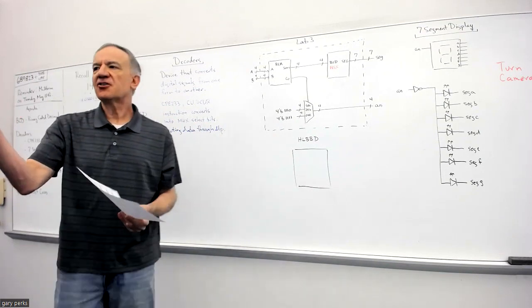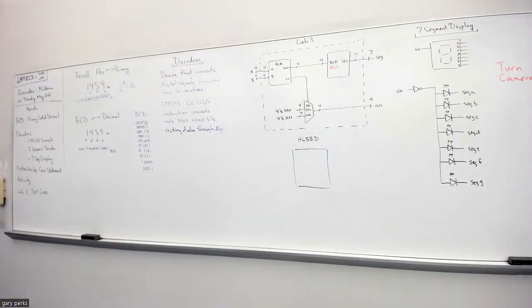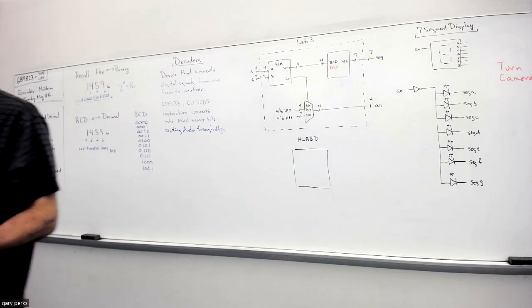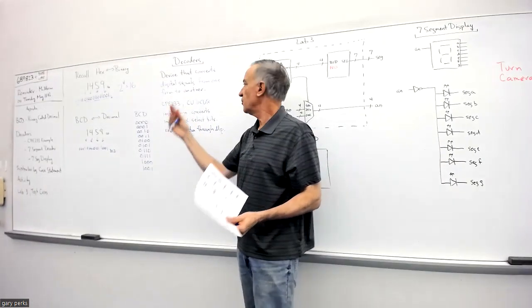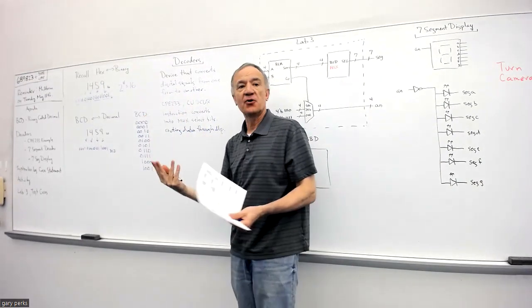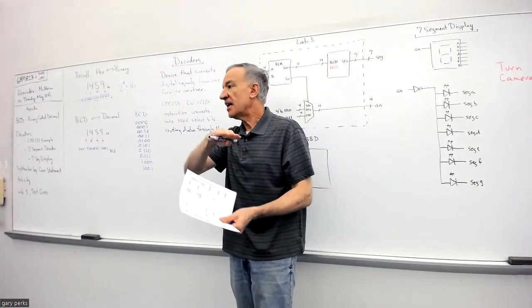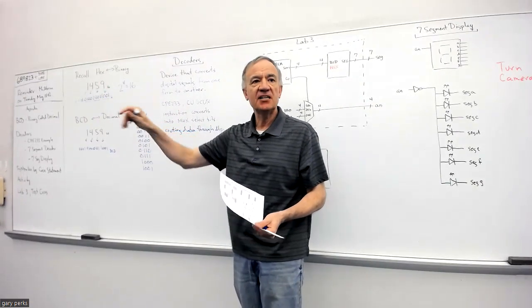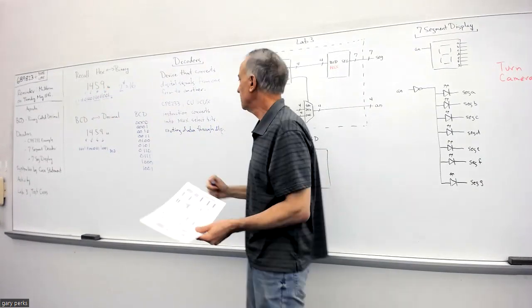Okay, so it's taking instructions, and then through the use of those outputs, which are connected to the select inputs of the muxes, it's how the data gets routed through the microprocessor. Okay, so that's an example of a decoder, right? It's taking one form of digital signal and instruction and turning it into another form, which are outputs that go to select lines that have the purpose of guiding data through the microprocessor circuitry. Okay.